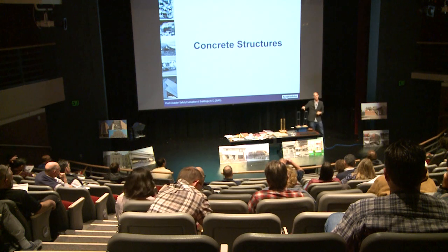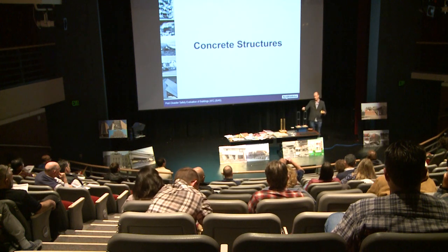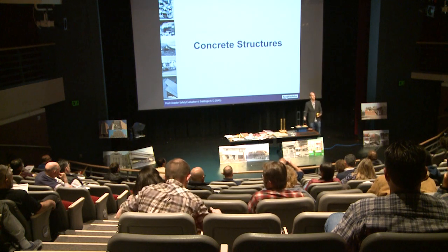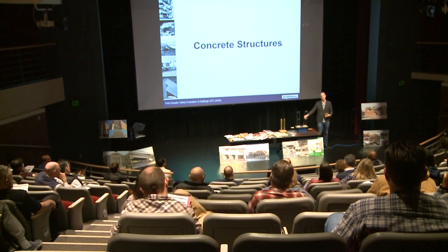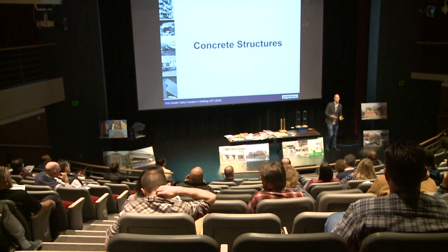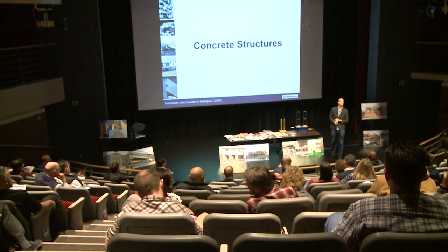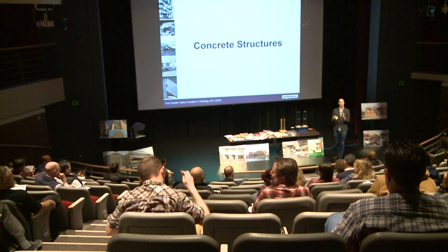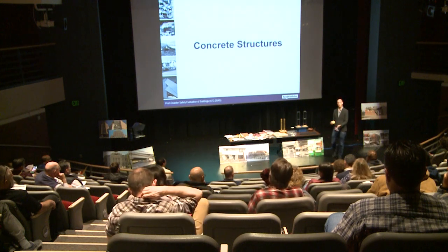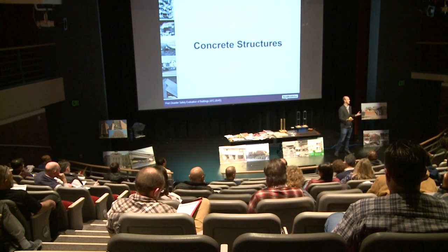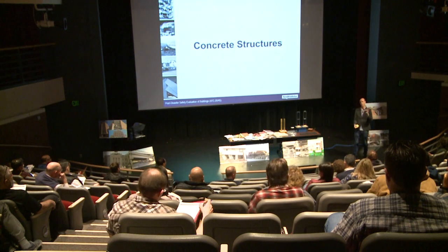Think of the ride that you're experiencing. If you're on the top here versus the bottom versus the ground, you're getting a much more amplified experience. And same thing with the non-structural systems. The suspended ceiling, your partition walls, et cetera, are moving more or getting more acceleration towards the top of the building. So there's likely going to be more non-structural damage the farther you go up.